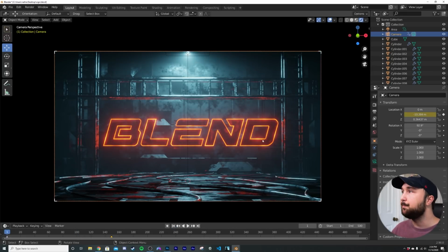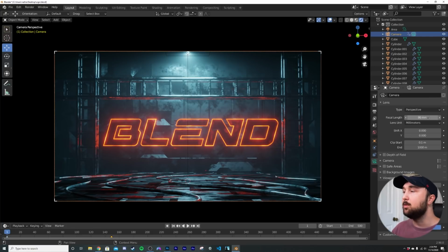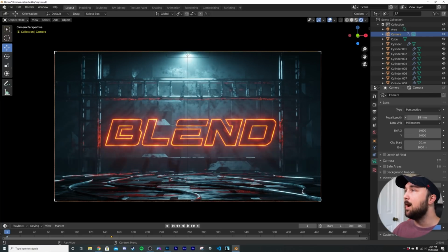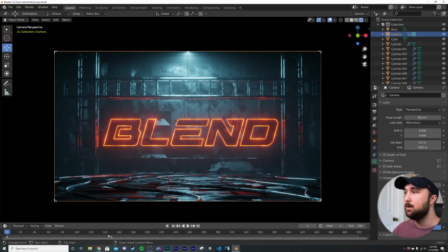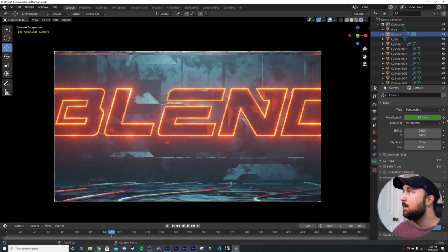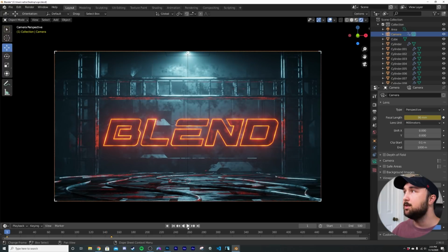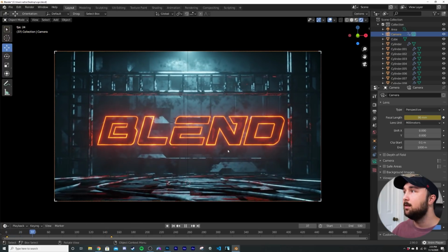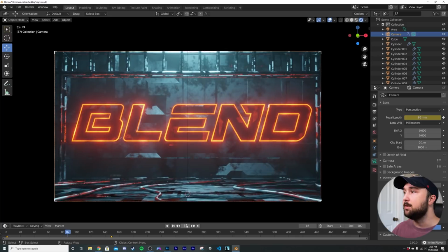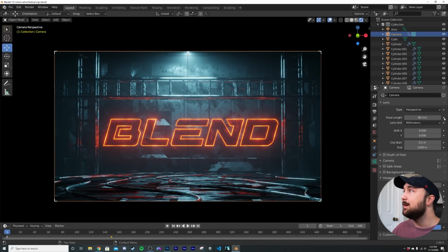Next thing I'm gonna do is click on the camera here and then play with the focal length. And what we're gonna do is widen that focal length once we get closer. So let's click on this, give it a keyframe, go to the very end, and then widen the focal length till we like how wide this section is here. And then watch this really cool effect. You get this really crazy effect. What I'm gonna do though, it's not very extreme.